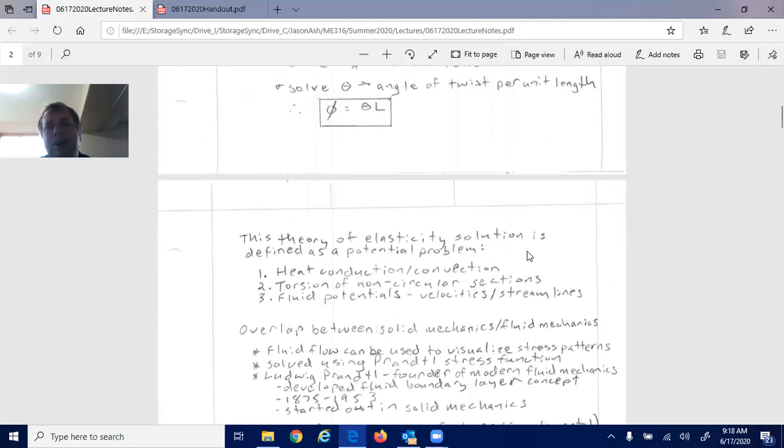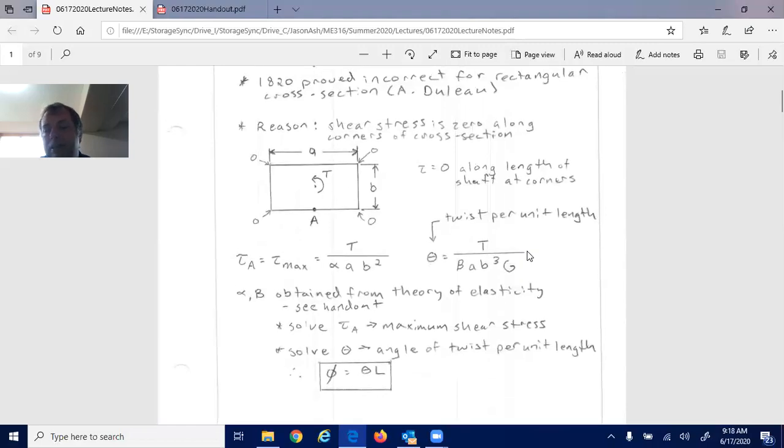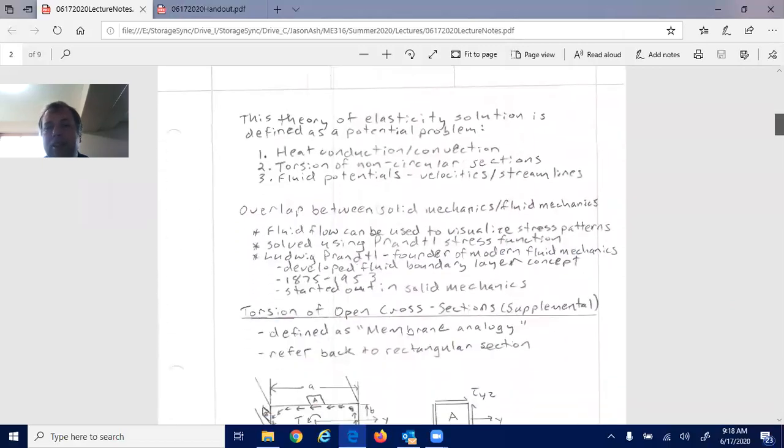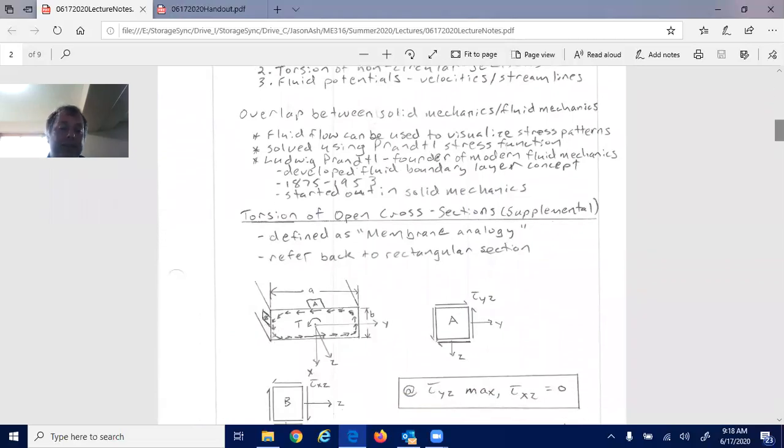And so this is really helpful in that oftentimes you use more than just circular shafts. You can often use angle iron, square tubing, or square shafts, I-beams, things like that. And so having a methodology to just estimate what the torsional shear stress is is beneficial. And so that gives you a table to look up some specific quantities.